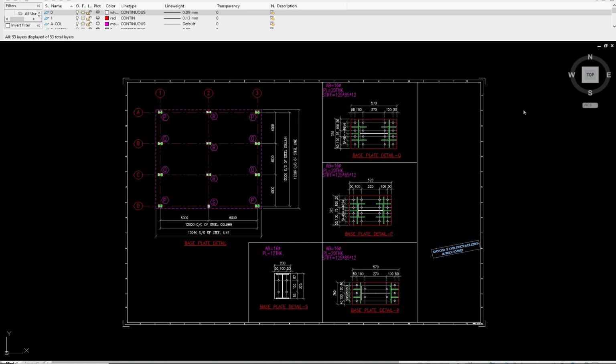For example, if you design a composite structure with a simply supported composite beam, the design of shear stud will depend on how much force is being transferred, or how much strength is being contributed by the equivalent concrete flange of the beam.